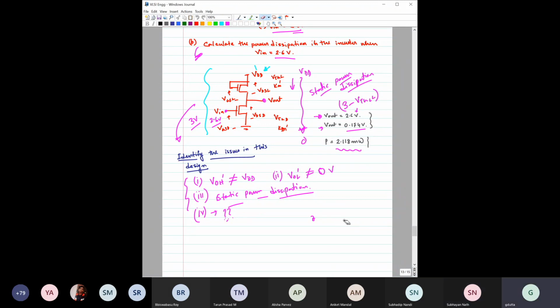Yes, sir. Okay, right. So Shubhayan, you asked about this part, and this is a good question. There will be two things. This is called the pull up network, you remember, right? And this transistor is called the pull down network, PDN. It is connected like this. From here you get the output. Here it is VDD. Here it is ground. And a common input is given to both of them.